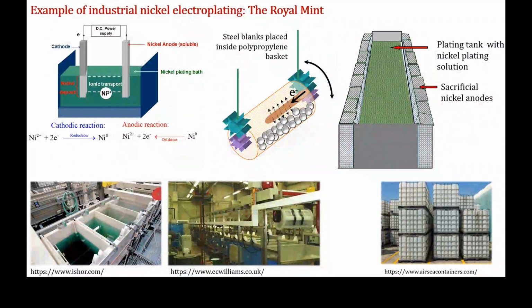But the problem is that the composition of the plating bath was not constant with time like it was supposed to be. And what was happening is that the salt from which nickel was actually derived, nickel sulfamate, the sulfamate ions underwent hydrolysis to form some ammonium. And this was happening at quite low pH, so pH 2 originally. And what they found is that the plating bath composition changed so quickly, and the quality of the deposits went down very quickly together with that.